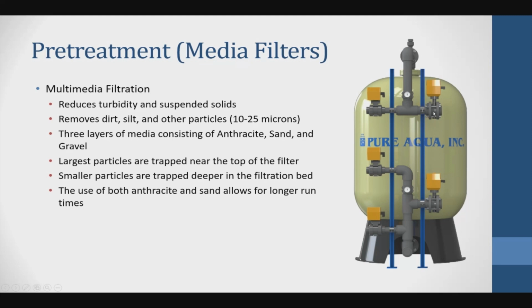The third cycle is the rinse cycle. The rinse cycle is exactly like the service water, where the water is being fed from here. So this valve is open, this valve is closed, this valve is closed, this valve is closed, and this valve is open. The benefit of having a short rinse cycle, when I say short, it's just 1 to 2 minutes, because we all understand the water is expensive, so we don't want to waste a lot of water. So it settles the different layers of media back to its position, and just in case if there is any accumulated dirt, that will be sent to the drain before we send the water to the reverse osmosis.